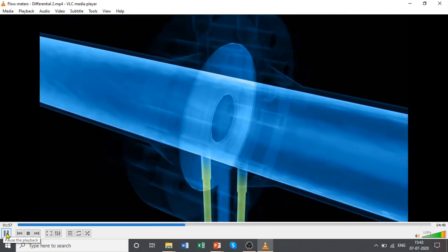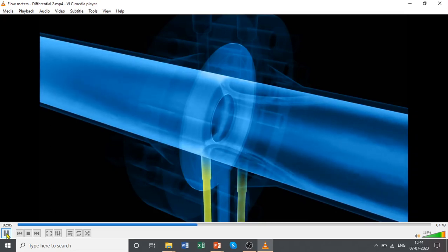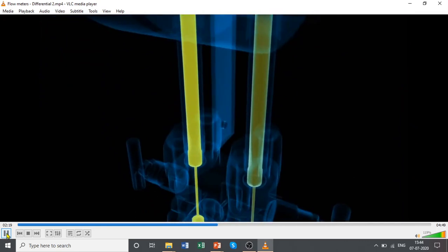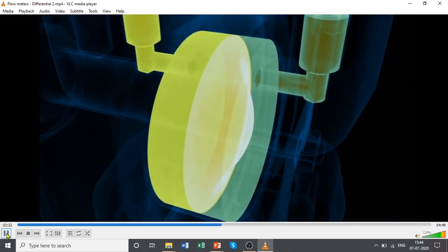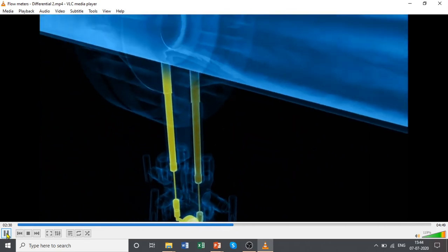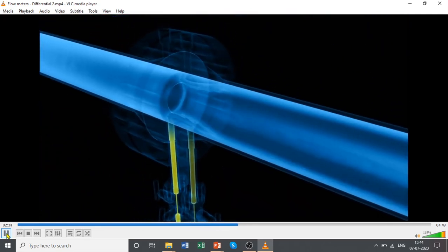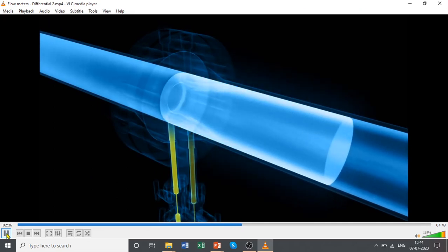If the fluid is not flowing, the pressure before and after the orifice plate is essentially identical. As soon as the fluid starts to flow, its velocity around the orifice plate increases significantly because of the restriction in the cross-section. At the same time, due to the laws of fluid mechanics, the static pressure at this point decreases. Consequently, different values are detected in the pressure chambers of the sensor: a higher pressure before and a lower pressure after the orifice plate. This pressure difference is a direct measure for the flow velocity, and thus the mass and volume flow in the pipe.